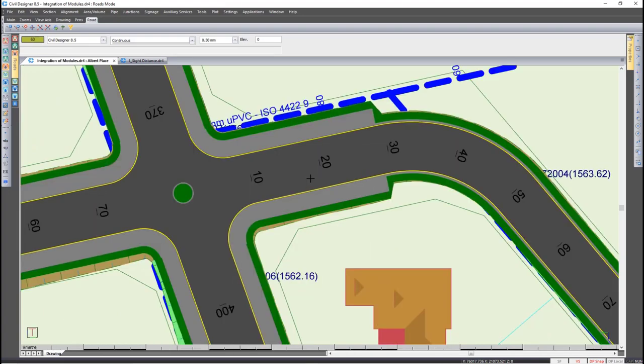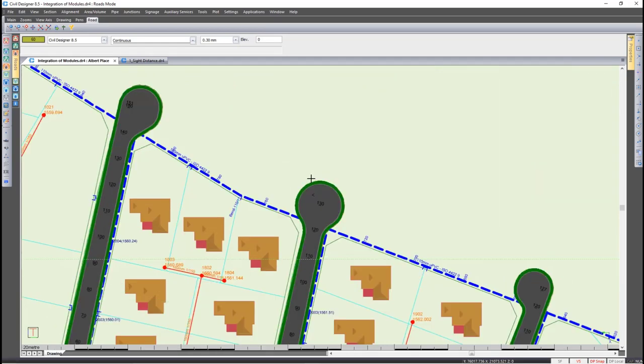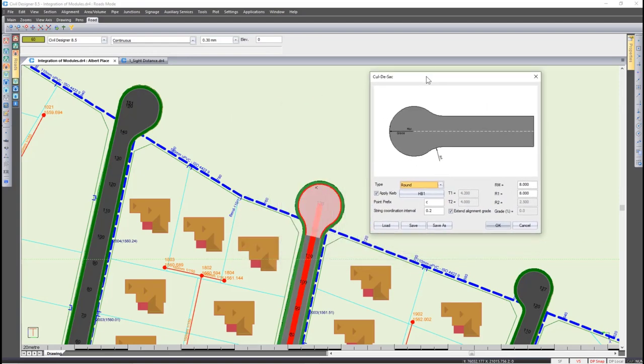In front of us, I'm going to show you the real-time junction previews for cul-de-sac and mini roundabouts. We will also look at the enhancements to the junction contour labeling functionality. I'm going to start off with the real-time junction previews for cul-de-sac. As you specify the different cul-de-sac types, you can see that the preview dynamically updates. If, for instance, you would like to change a radii of your cul-de-sac, automatically the preview will be updated. So straight away you see what the end result would look like.